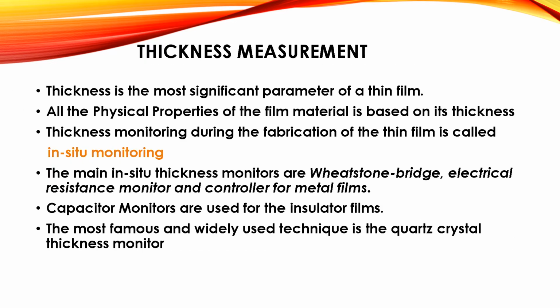Thickness measurement is the most significant parameter of a thin film. All the physical properties of the film material are based on its thickness. Thickness monitoring during the fabrication of a thin film is called in situ monitoring. The main in situ thickness monitors are Wheatstone's bridge, electrical resistance monitor, and controller for metal films. The capacitor monitors are used for insulator films. The most famous and widely used technique is the quartz crystal thickness monitor.